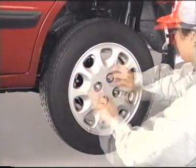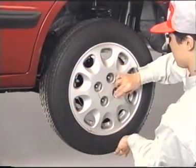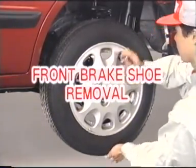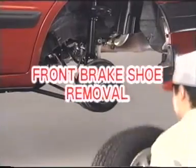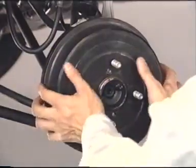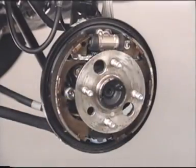Distorted brake shoes, sticking, or oil or grease on the lining could cause brake trouble. The brake shoe must be replaced if necessary. Release the parking brake and remove the front shoe.